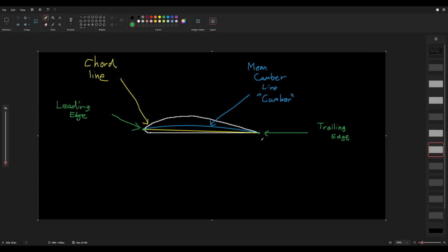of flaps. So the flaps on an airplane are on the trailing edge of the airfoil and are responsible for extending, or I should say altering, the camber of the airfoil. So they might come out on the back as a little flap that, instead of going like this, goes down like so, tilts down. It's not a very great drawing.